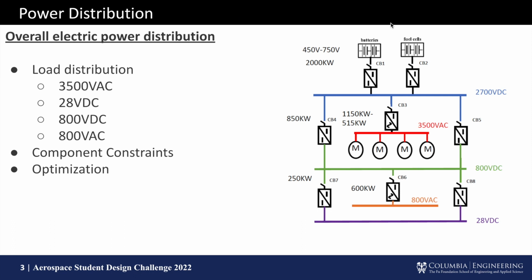Shown to the right is our electrical schematic of our power distribution with 4 different voltage lines. Each line will support various loads in our aircraft and were derived from component constraints. We first started with our motor and reverse engineered the battery sizing and power output. To better optimize this system, we needed a better battery energy density, but also more efficient converters with better switching properties.